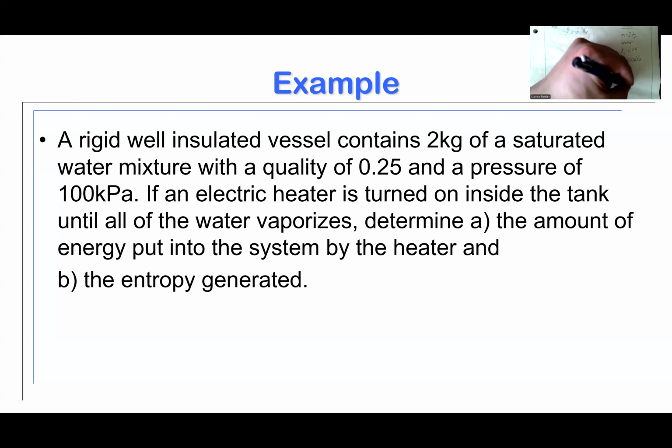And it's well insulated. So there's no external heat crossing the boundary. The only energy crossing the boundary is going to be work, and we're going to assume that it's a closed system. They've not said anything about mass crossing the boundaries. Often just with a rigid vessel, that's what we're looking at.